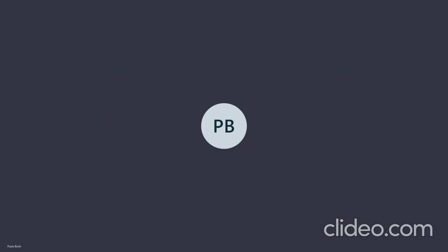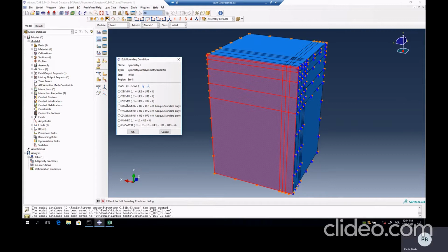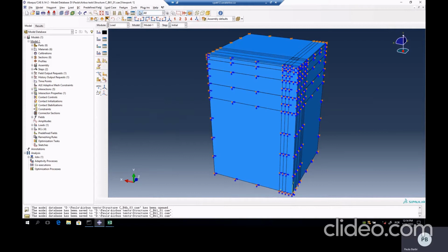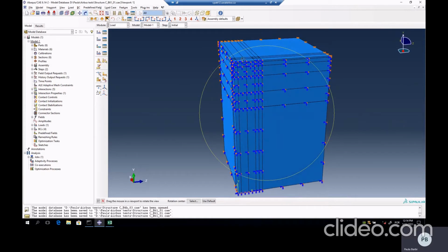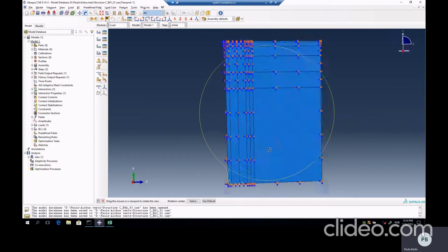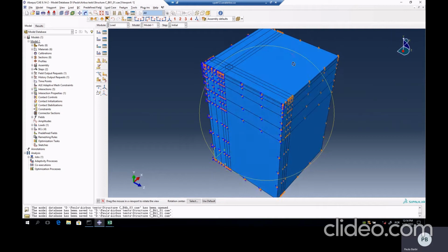Right, okay, so we have the wall selected. Now we click OK and we select this option. So good, we're good. So we have the load applied, we have the boundary conditions in all directions we needed. Now the last step here would be to do the mesh.